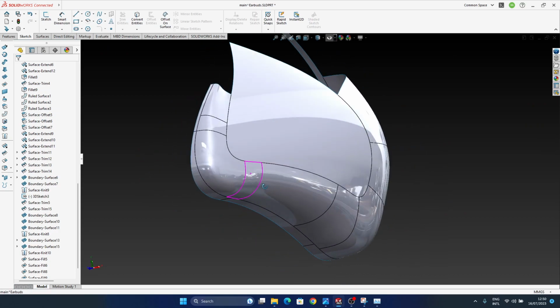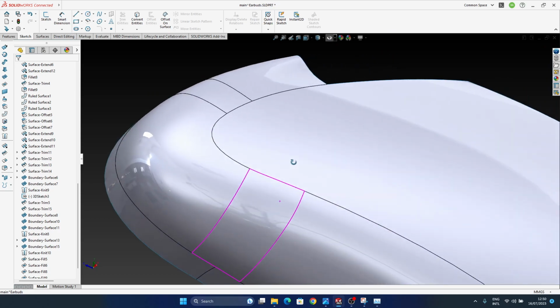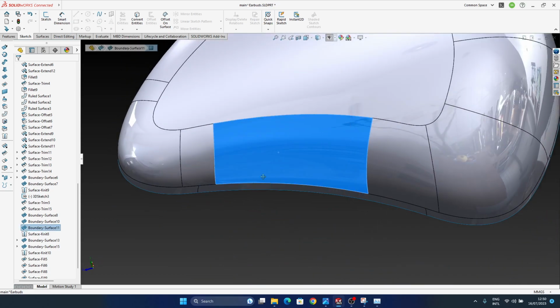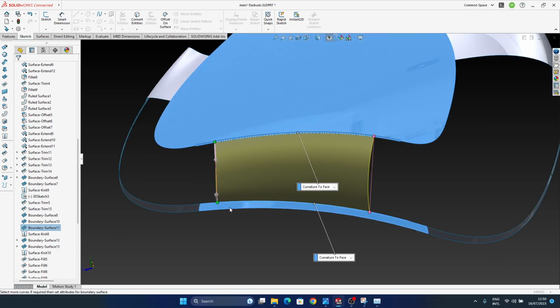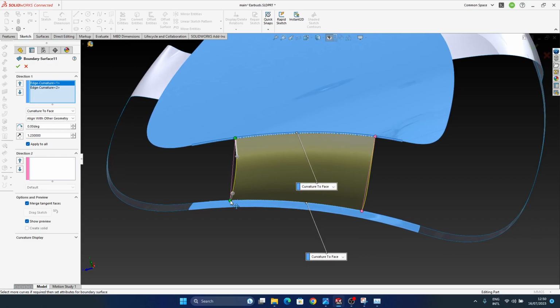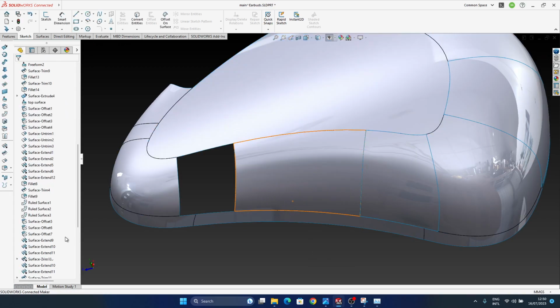So opening this up. Yeah, and I can see, so it's the constant transition. Constantly is the transition that is problematic. It's quite sharp transition, so SolidWorks doesn't really have enough space to smooth it out.